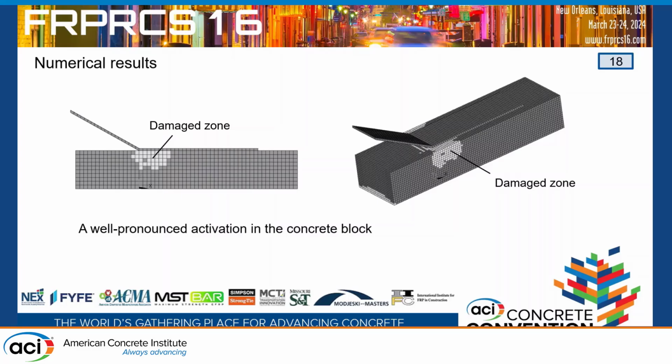These numerical results show that concrete degradation is not limited to a narrow zone near the adhesive layer, and potentially, theoretically, this may affect the whole concrete structural element which is reinforced with FRP.